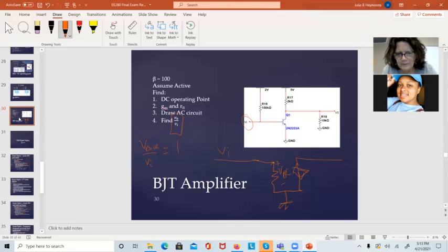Whatever voltage I have there will be VBE. And then at the output, you get this parallel combination of resistors. You get the current source, which is GM VBE. It's going into the wrong end of this thing.